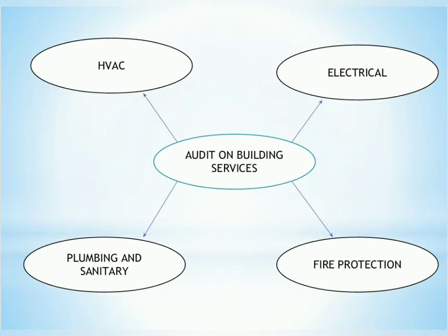For air handling, the problems are air distribution system efficiency, noisy operation and excessive vibration. In air distribution and terminal systems, the common problems are dirty and moldy ductwork and filter media choke at the air terminal. And last one is the indoor environment: leakage in the roofs and walls makes the ceiling dirty and affects the indoor environment.